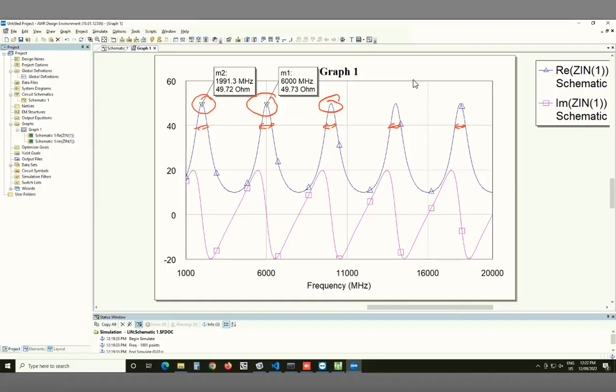Yeah. So earlier we had seen that the fall off was happening when we were considering lambda by 4 versus 3 lambda by 4 at 60 gigahertz. And now we are just replacing the parameter. Because every time the transformer is going from lambda by 4 to 3 lambda by 4, the frequency is also going from F to 3F, and so on, 5F, 7F, and so on.